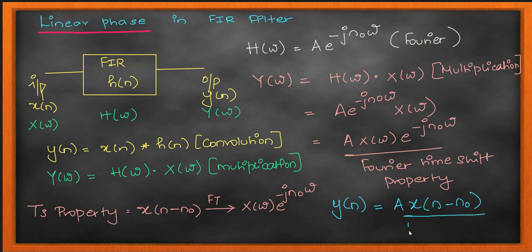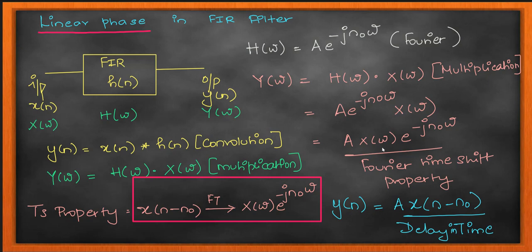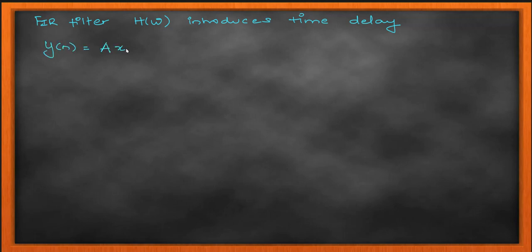So you see here the delay is what is introduced by my filter. My filter e to the power of j n0 omega introduces just a delay, x of n minus n0. We will see in detail because this phase is important. This delay n minus n0 makes sure that my FIR filter operates on the input signal and produces an output signal whose frequency is not different from the original signal, and not different at different places. That is what this linear phase ensures.